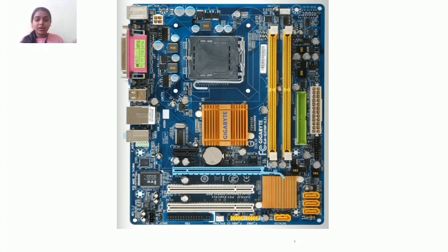Unlike a backplane, a motherboard usually contains significant subsystems such as the central processor, the chipset, input, output, and memory controllers, interface, connectors, and other components integrated to the general line. Motherboard means specifically a PCB with expansion capabilities. As the name suggests, this board is often referred to as mother of all the components attached to it, which includes the peripheral, interface cards, daughter boards, sound cards, video cards, network cards, host bus adapters, TV tuner cards, and a variety of other custom components.